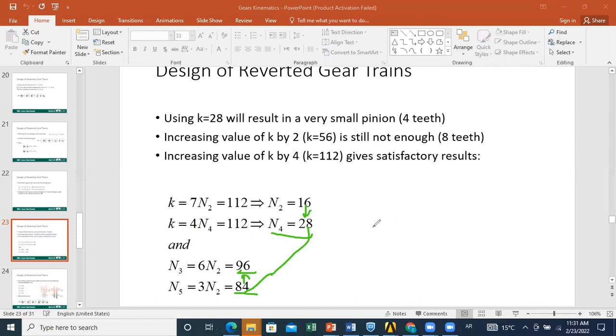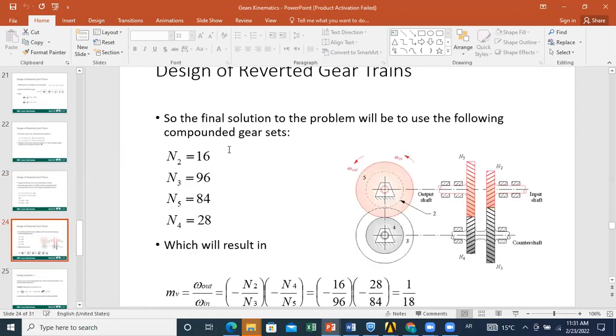Okay, so always as the pinion size increases, the range of sizes for the gear for no interference will also increase. Okay, so whenever you have N4 larger than N2 and N5 smaller than N3, and 2 and 3 was acceptable, then surely 4 and 5 will not lead to interference. Any question until here? Okay, now so we say that these are our possibilities.